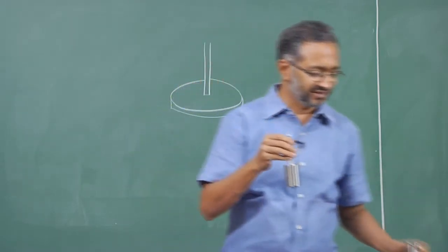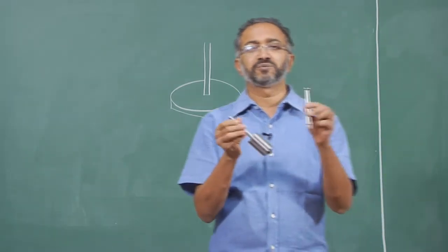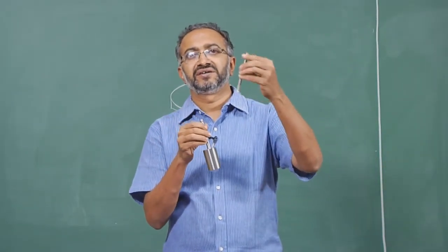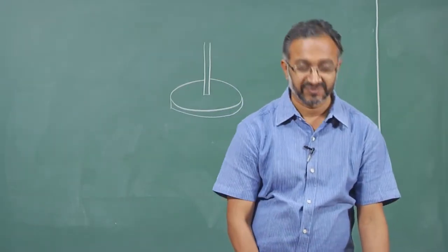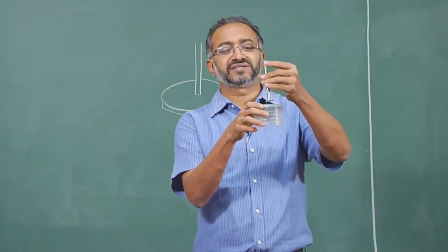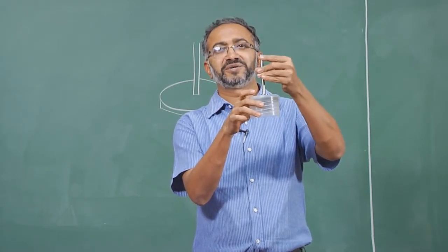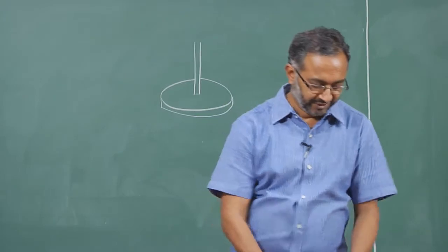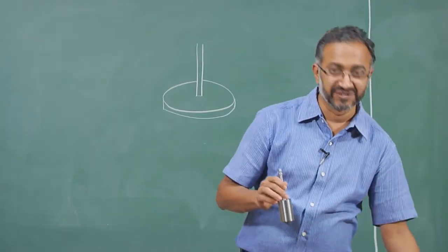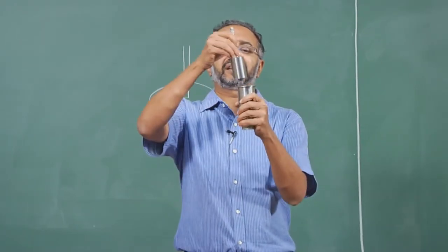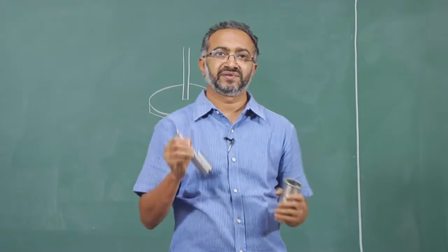So the question is, why would you use this kind of geometry compared to parallel plate, which we saw earlier? In the case of parallel plate, you can see that the overall area over which shear is being applied is this circular area here. So sample is here and then shear is being applied. While in this case, what you have is this overall cylindrical area over which shearing takes place.